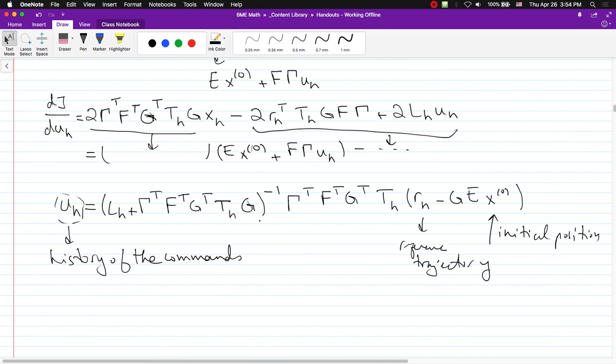And so why is that useful? Because when you generate some action, the consequences of that are noisy. You can't know for sure where you're going to end up. And so therefore, you need feedback. So you're going to sample what happened and say, okay, I am here now. What is the best action to do? And so we'll see that we're going to bring back the Kalman filter because you produce an action, you generate a consequence, you measure something, and then you have to combine what you measure with what you expected. And that becomes your estimate. And based on that and the Bellman equation, together you now have the best action possible.